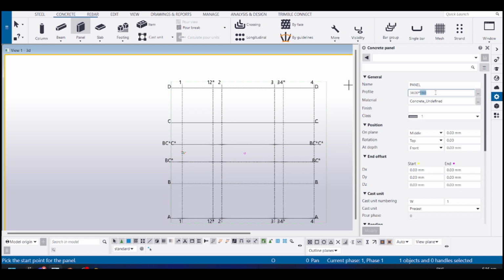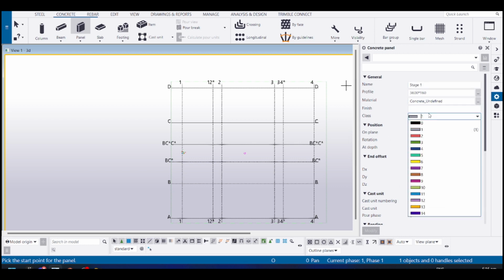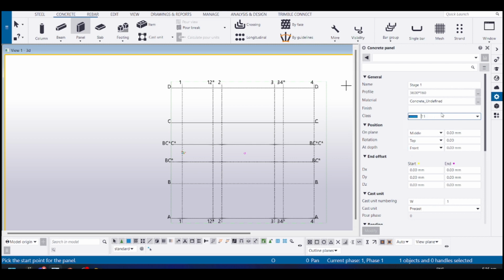a twin wall, so I'll have 2 shells, so I'll call this as stage. So it has stage 1 and stage 2. So stage 1, and I'll give it a color. Suppose I give it as blue. 11. I'll keep it 11 as stage 1 and 12 as stage 2. And this shell is basically just about 65 thick. I'll take it as 65 skin.